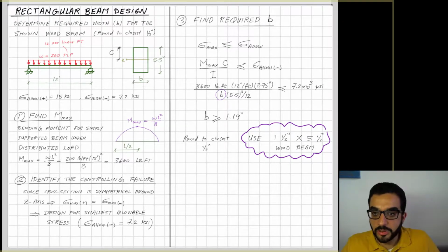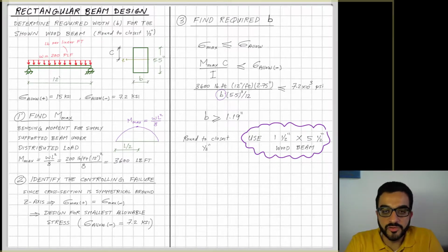So it's that simple because the problem is really simple. It is a simply supported beam, so they have only positive moment happening. There is no length of the beam subject to a negative moment. And even if this is the case, we have a symmetrical section. It's a rectangular section. So always the positive and negative stresses within the section are equal. Top and bottom stresses are the same because the centroid is in the middle of the height.